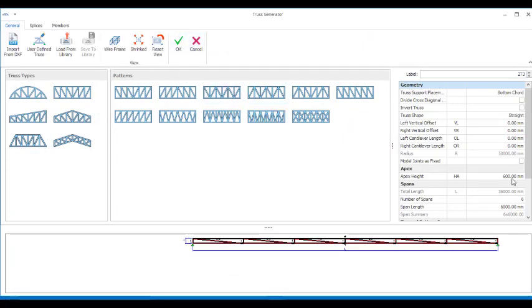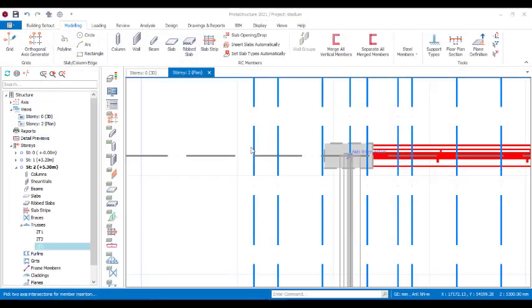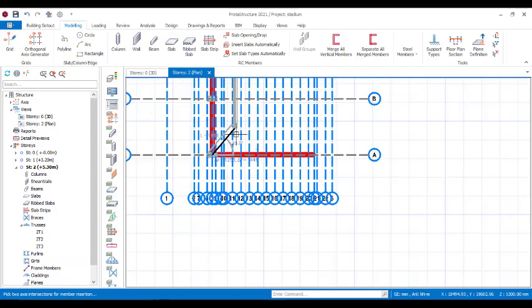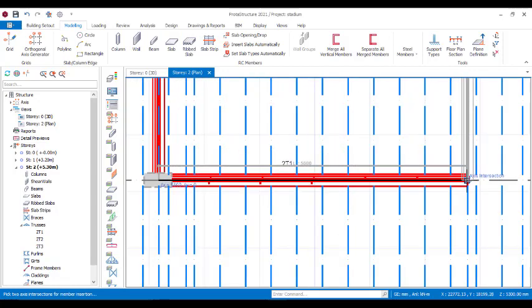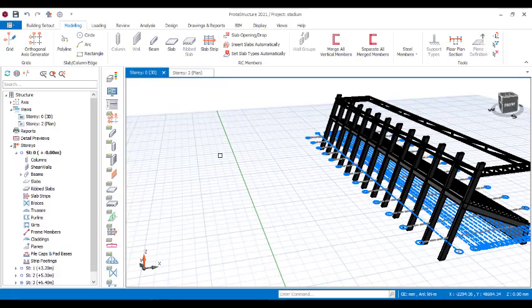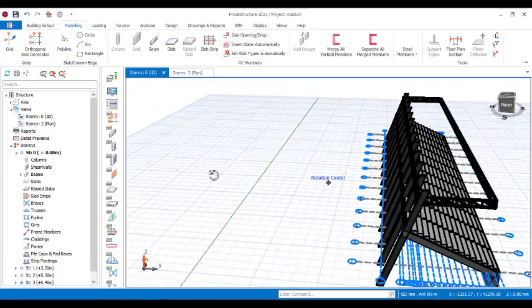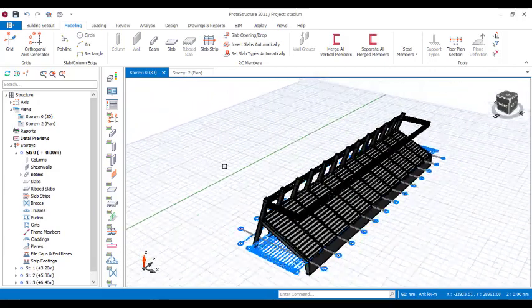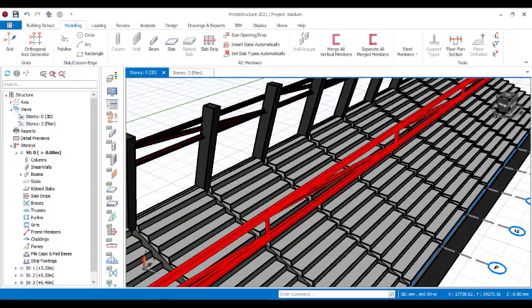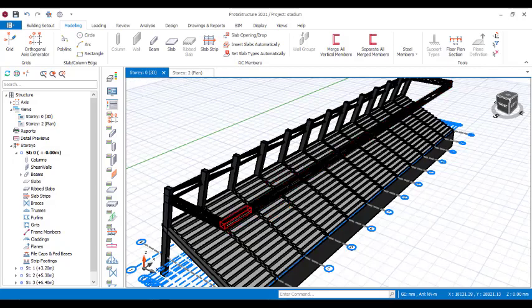You can see the 600 that I edited last. So just click on OK. You should have that, and then we are expecting one more at the front, which is this point. So drop it there, and then you can escape that. So let's see in 3D. This is exactly how we have it. You can see how the truss looks.